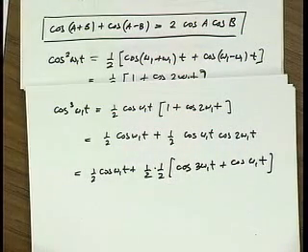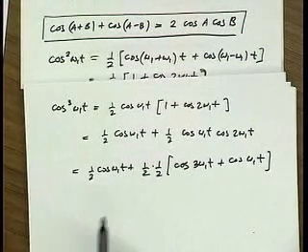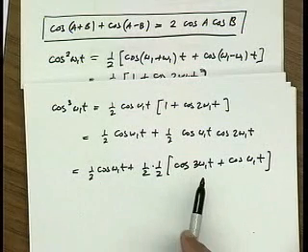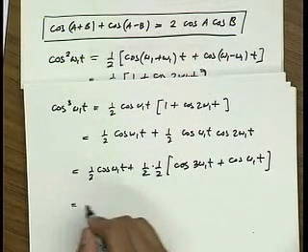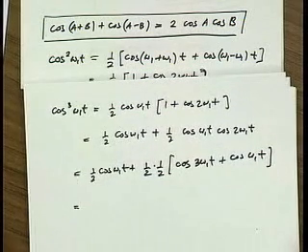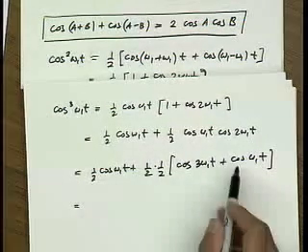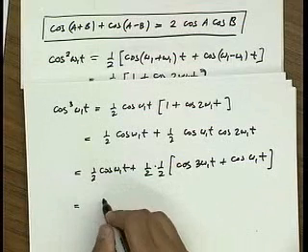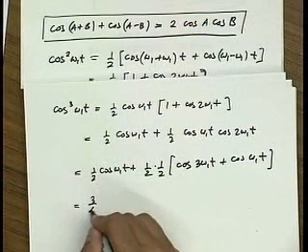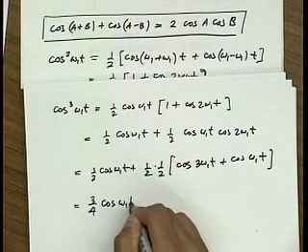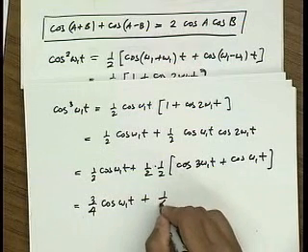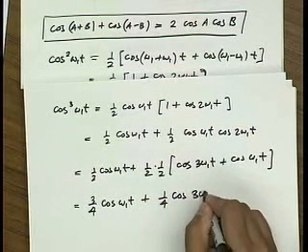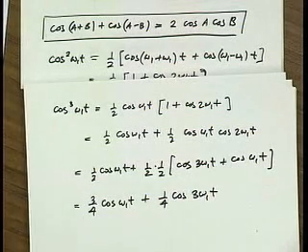So we see that the cubic generated fundamental and third harmonic. That, of course, matches the results we did last time when we did the binomial expansion. If I sum here, I get 1/4 plus 1/2, or 3/4 cosine omega 1t plus 1/4 cosine 3 omega 1t. Okay?